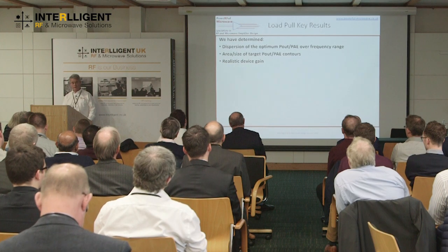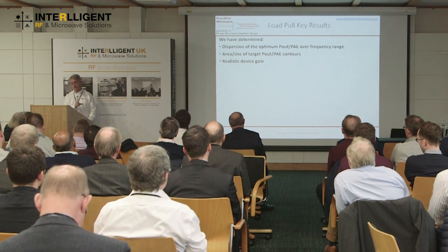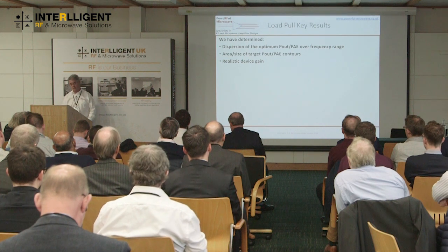We know the sort of impedances we're looking at, and that's so important. And we know what sort of realistic gain we're going to get across the band, which is important to specify in the driver device. Remember that we've been doing load pulls, so we haven't taken into account at this stage any of the device losses, or any of the matching circuit losses. You need to allow for those.